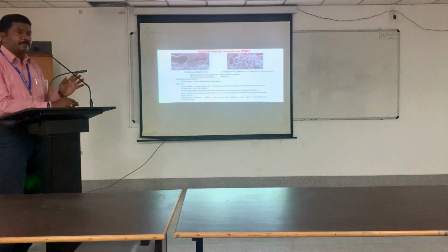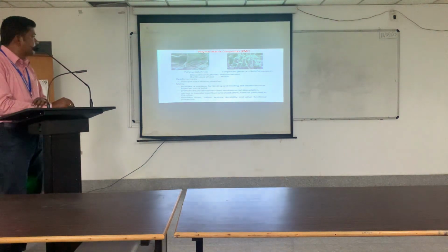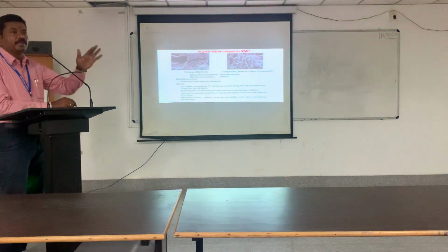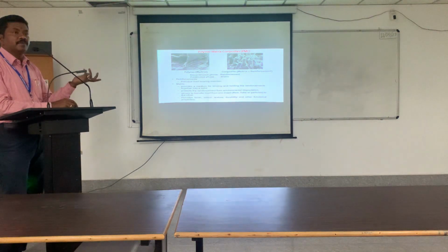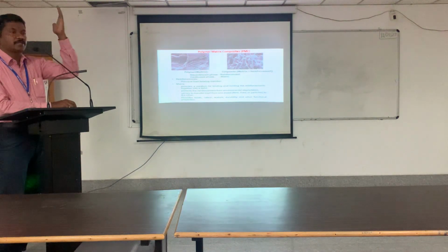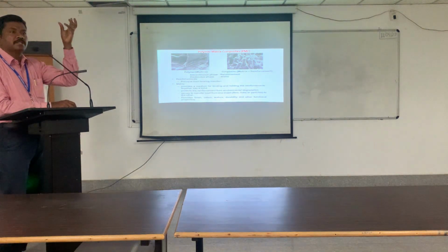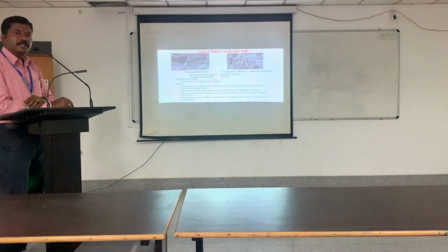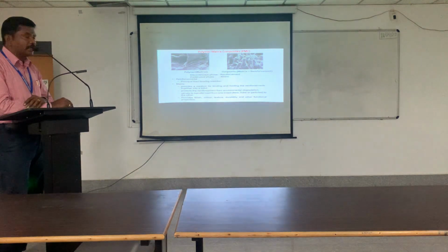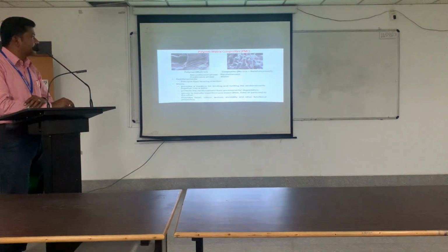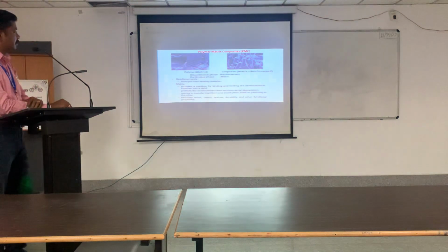In the case of polymer matrix composites or metal matrix composites, the matrix material is classified as the continuous phase, since it has continuity throughout. Whereas in the case of reinforcement, continuity may not be there. In the case of continuous fibers, you can see the fibers are continuous. If it is particles, you cannot see the continuity. That is why the reinforcement comes under the discontinuous phase, whereas the matrix comes under the continuous phase. You can see this is the matrix alone, and this is the composite, with fibers surrounded by the matrix. This is matrix and reinforcement. This we have already seen.